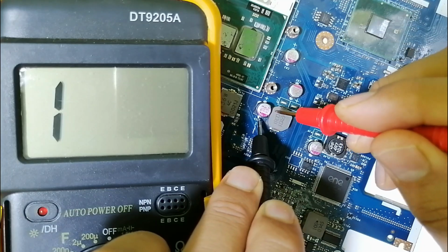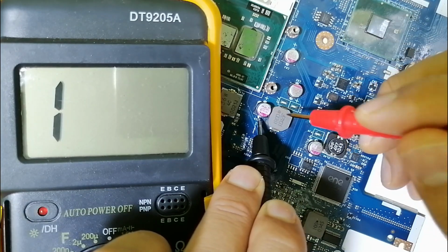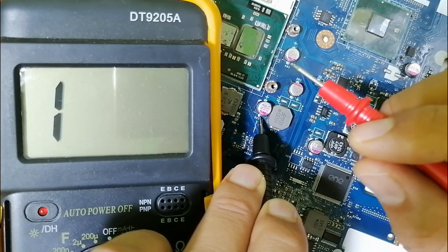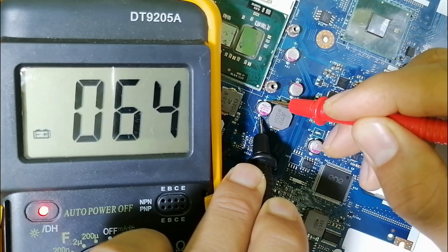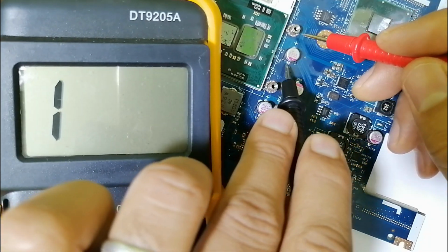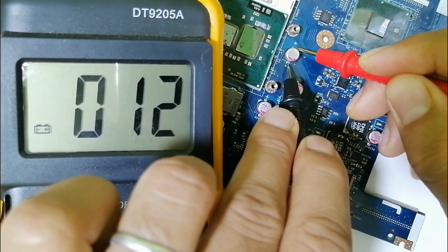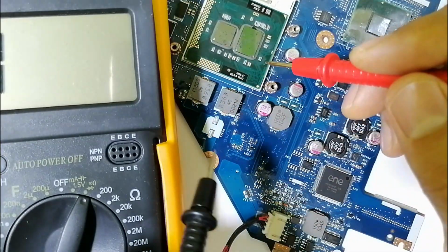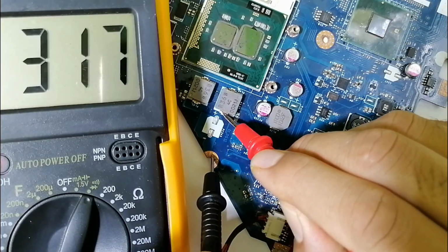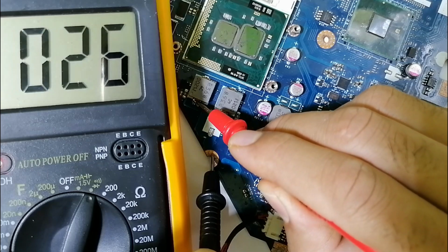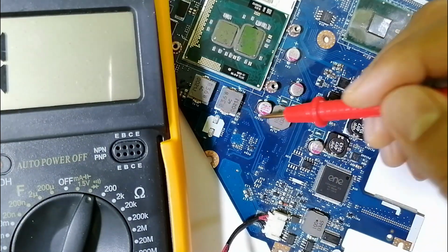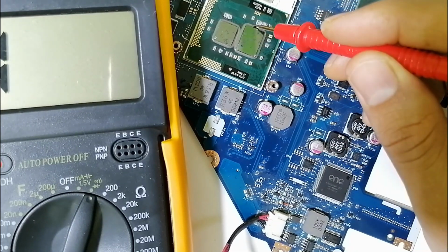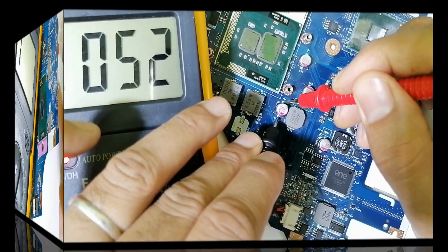Here we have a trick that you should understand. I will share with you this very important tip that many technicians don't know about this kind of shorts. We can find this one also with the same reading. Is it a short? No. Also, this inductor will give the same reading in the multimeter. If we put the black probe here and the red probe here, you see? This is not a short. This is basically the resistance of the processor, because the processor is installed in the motherboard, and we get this value.